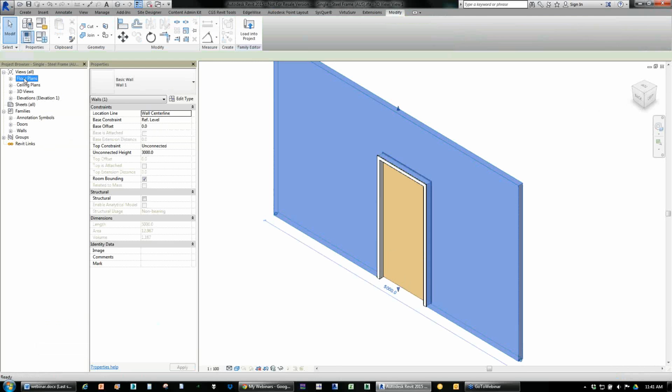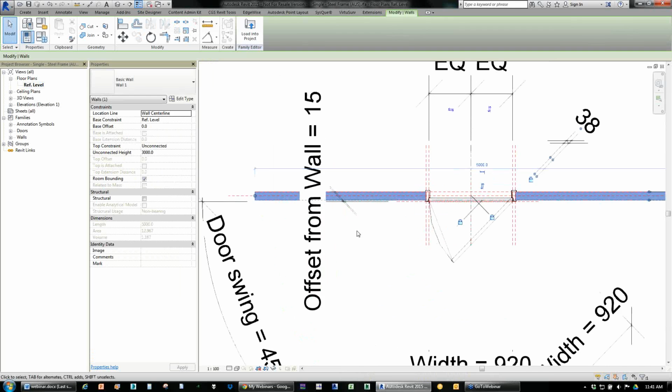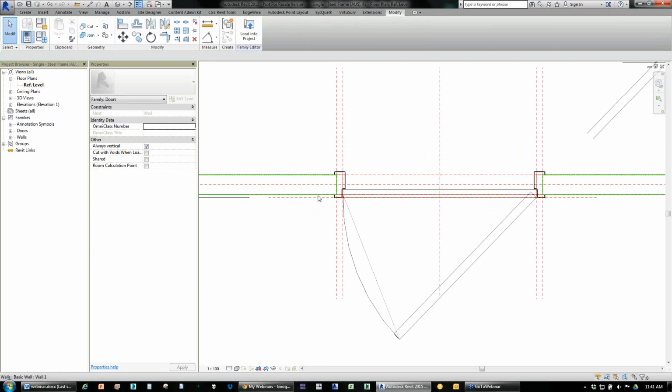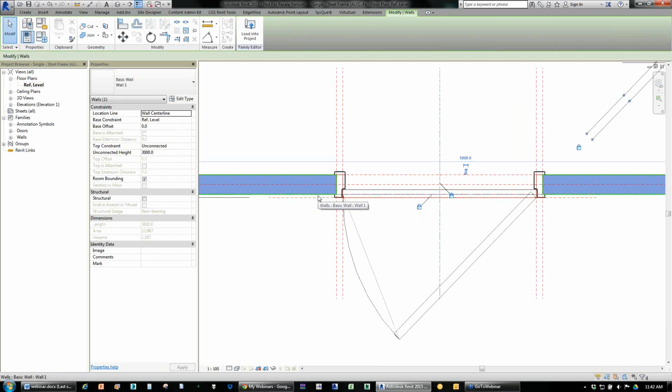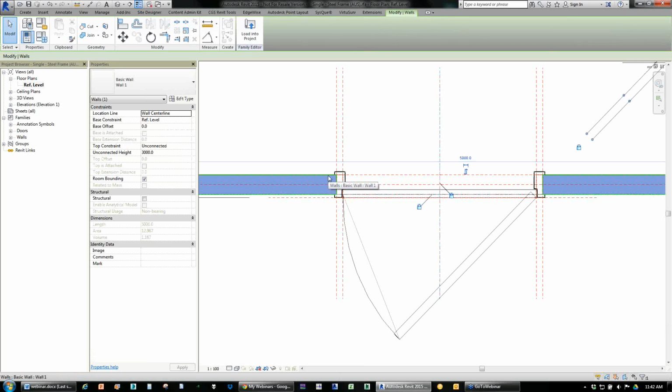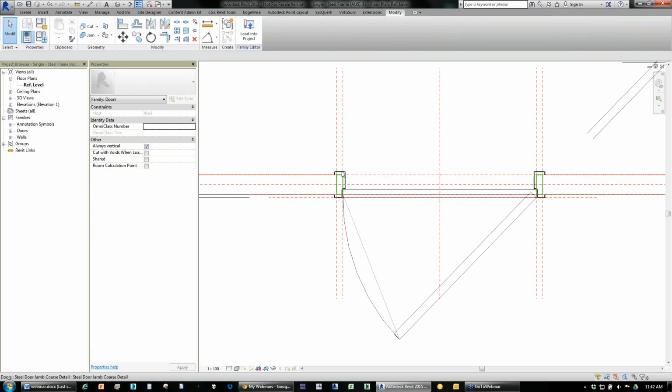Now that is actually what's referred to as a generic host. So in a Revit family, in this particular case, it's a door. Doors are wall hosted. There's a generic host that's placed here, or that appears inside the family, and then I place my geometry and so forth to represent the door. And when I place this into my project, Revit swaps out the generic wall and places the component family into the actual wall that's in the project.